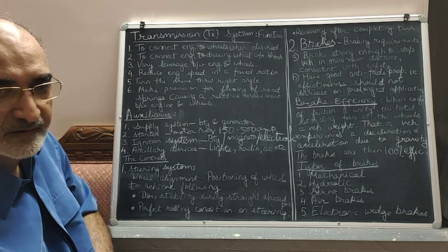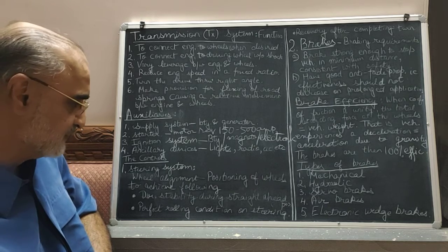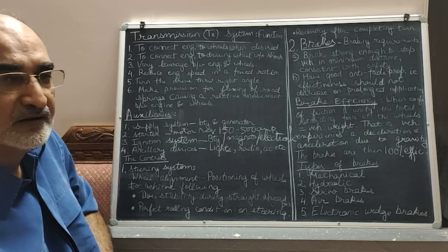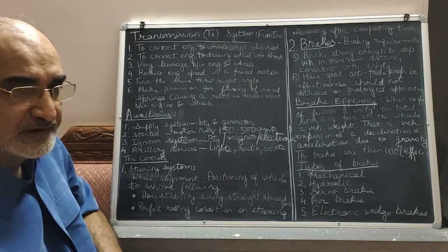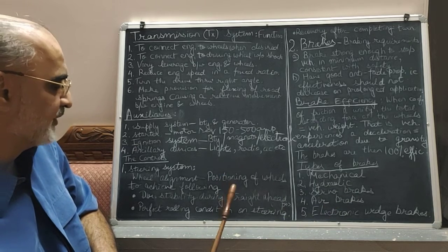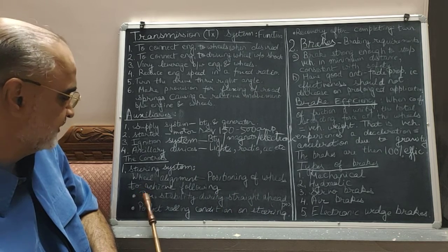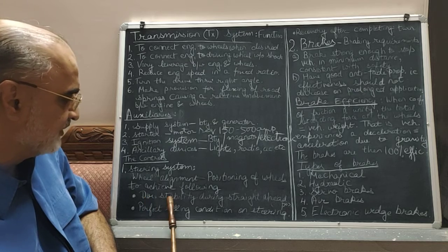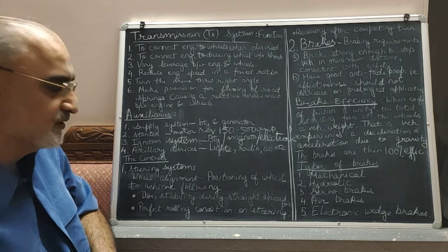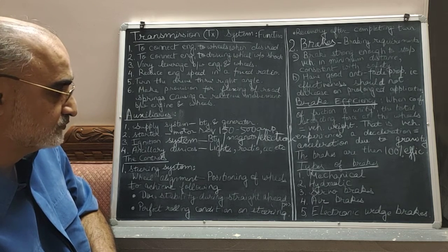We all know we go and align our four-wheelers periodically, from time to time, every 8,000 to 10,000 kilometers. What is wheel alignment? Nothing but positioning of the wheels, correct position of the wheels, correct angle of the wheels to achieve the following. Firstly, to achieve directional stability during straight ahead position. The vehicle is moving straight, it should continue to move in a straight manner.